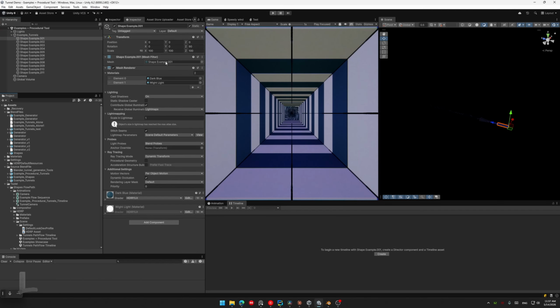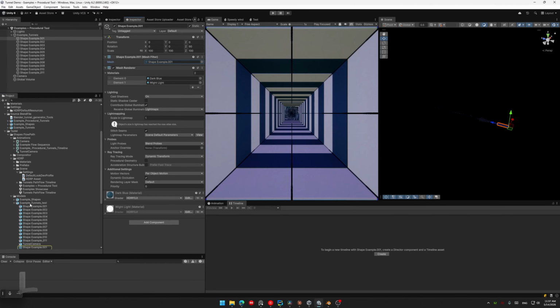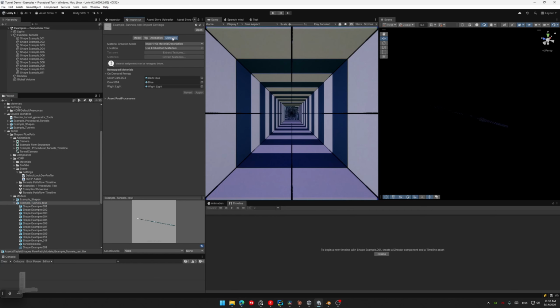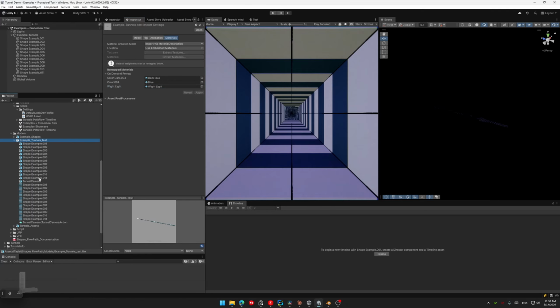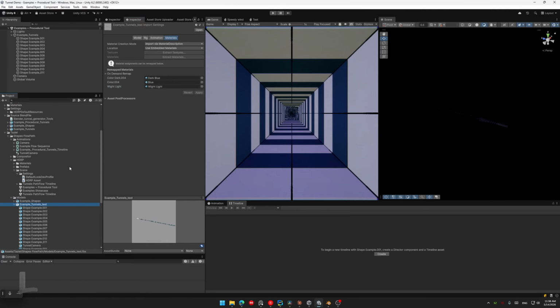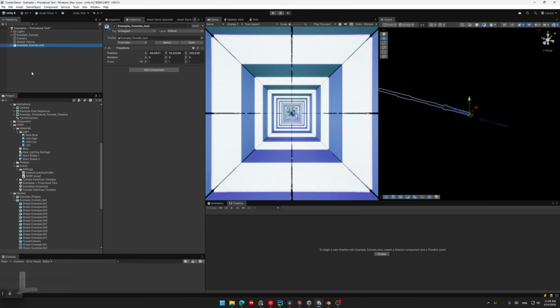Next, what we need is control of the emissive material we're attaching here. To override that, we're gonna go to the FBX export file that we made. Go here, go to the material tab, and select that light material. We're gonna replace it with something we can control. I'm gonna use the one I attached on the asset, light, and here's the LED material. Apply. So we're gonna drag it again.